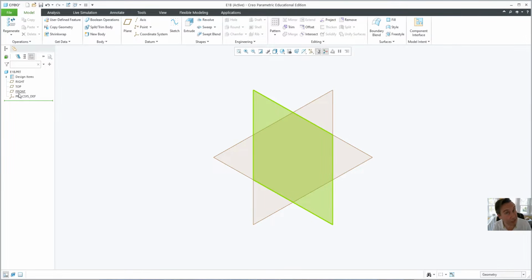It's not always easiest, but the thing is that I tell students, don't worry about it too much right now. Okay, go ahead, and when you want to start sketching on a plane, that's what we're going to do here. You click on the plane, and you get this quick launch toolbar of different features. So, for example, there's edit the definition. We're not going to do that. There's sketch, and there's extrude and revolve. So it gives you some foundational features.